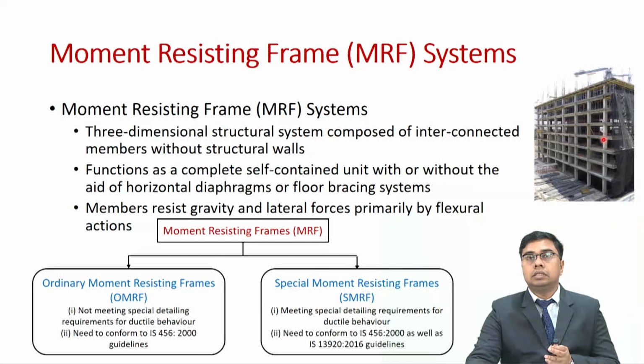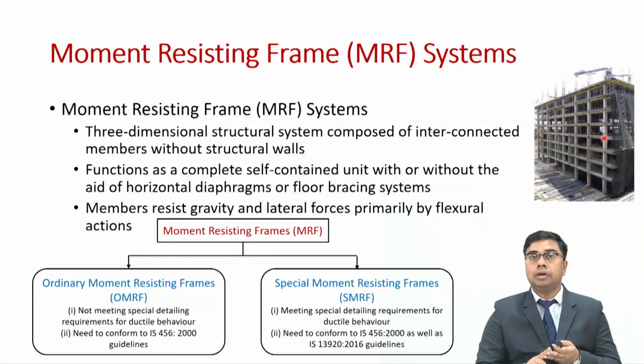We have already discussed in the previous week, in the capacity based design, that the collapse of one beam does not lead to catastrophic failure of the structure as a whole. So the first failure is expected to be in the beams in the form of plastic hinges, not the shear failure. Shear failure is still a brittle mode of failure, so that is to be restricted.